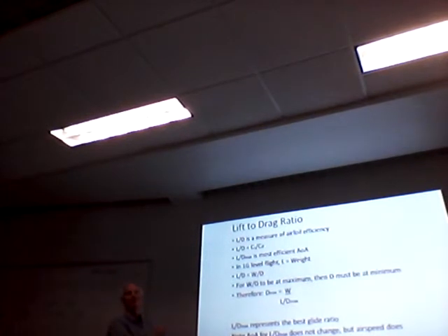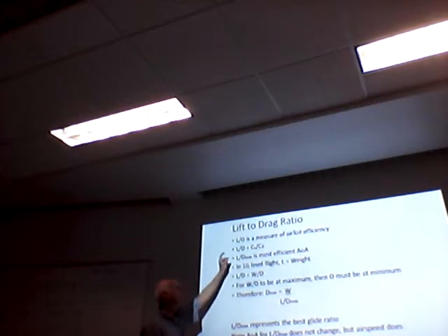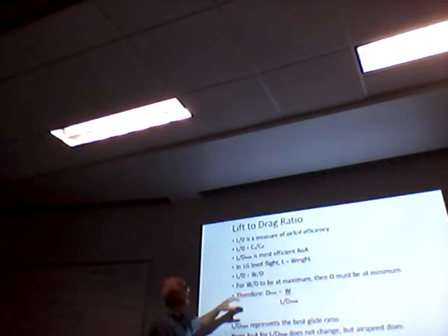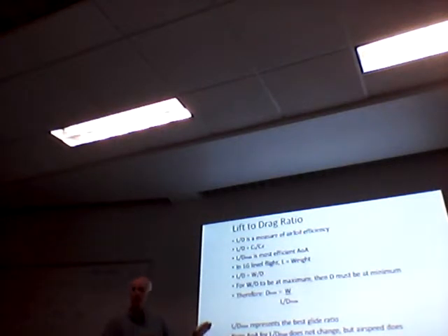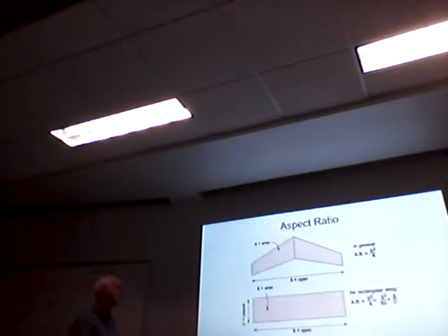Questions can be derived off of this slide. Okay? So, lift to drag ratio, airfoil efficiency, that's a good thing to know. L/D max, most efficient AOA, does a lot of different things. However, as we'll see later, there's differences between min drag point on the thrust required versus the power required curve that I'll highlight later. But jet aircraft have different performance things at L/D max or min drag than do other aircraft. So we need to make distinction between those two.